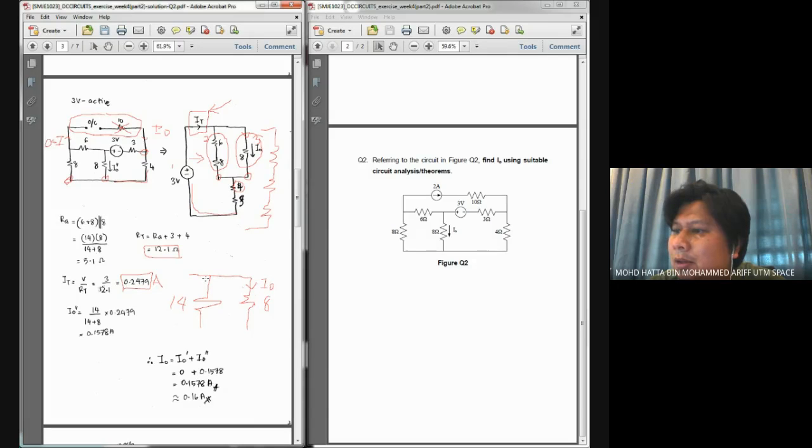And originally I have this I total. Okay. And I use this kind of equation where to get current here at the right hand side, what you need to do, you need to consider the resistor at the opposite branch divided by the sum of these two branches and times with the current coming into these two branches. So this is what happened when we try to calculate using current divider rule.